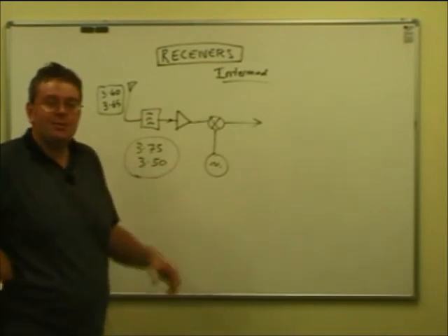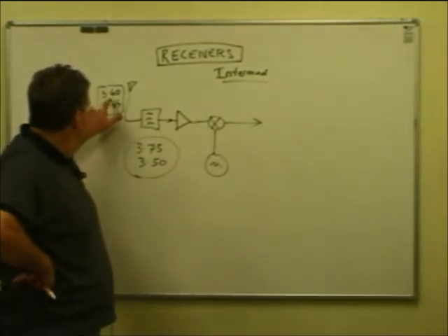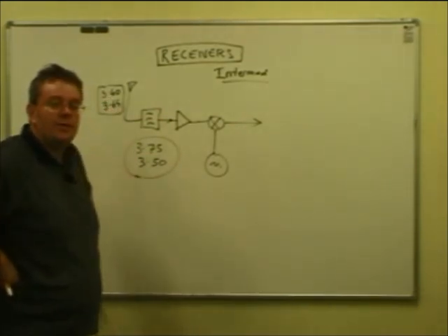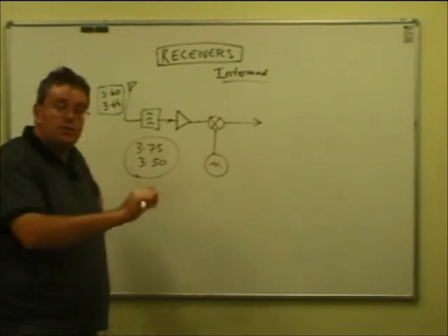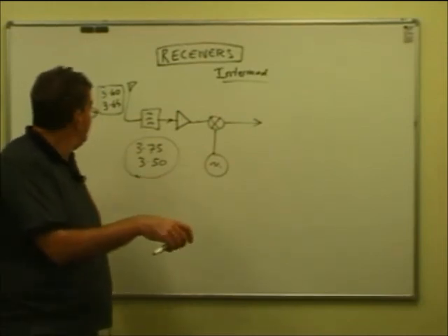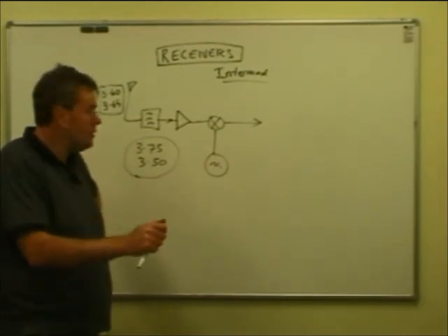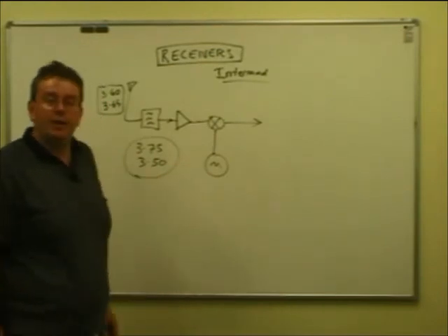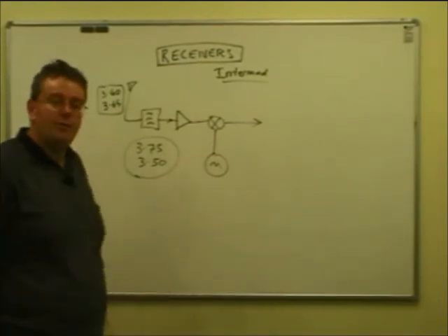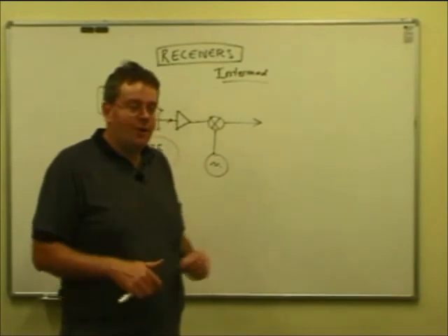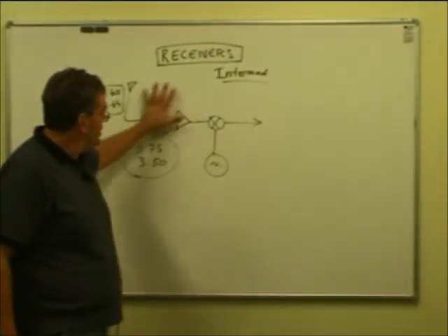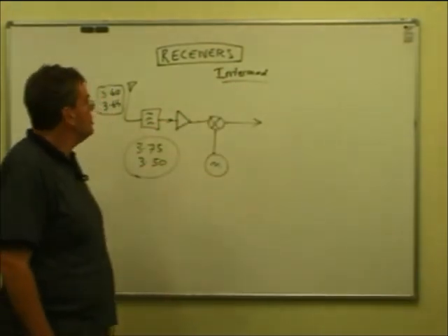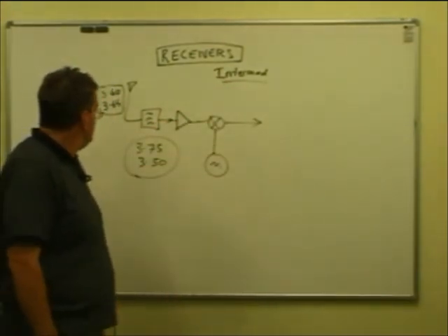You could do this as a demonstration in the class. You put the 3.6 and 3.65 megahertz signals into the receiver, just manufacture them with signal generators and have them reasonably strong. And sure enough, as you tuned around on your receiver, yes, you'd hear the signal at 3.6 and hear it at 3.65. Tune down to 3.5, you could hear it as well. Tune up to 3.75, you could hear it. So the radio is actually creating new signals just because of a relatively poor design in the front end. And that's called intermodulation, which can be a real problem.